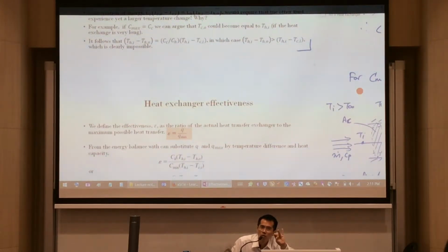If you are missing only one, so you've got three of them, there must be one pair of inlet and outlet and another inlet or outlet. It's possible that you could solve using LMTD by finding the fourth, unknown temperature. In some of your tutorials, you get to practice that.